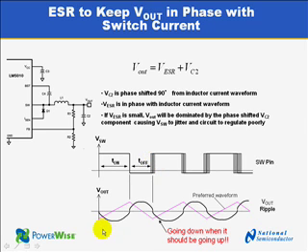The timing diagram below shows the output voltage ripple under two conditions. The pink one at a high ESR with a stable regulation. The black one with a low ESR: a sinusoidal ripple waveform with a poor regulation and a jitter. So for stable regulation, output voltage ripple amplitudes of up to 100 millivolts could be necessary. This could only be achieved with high ESR values. But this means such a high voltage ripple at the output may not be acceptable for all applications.